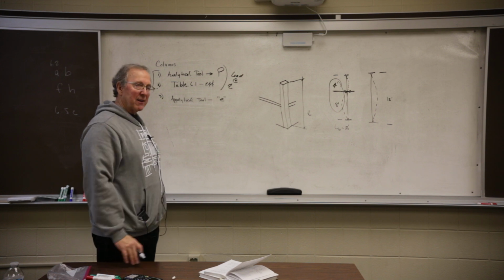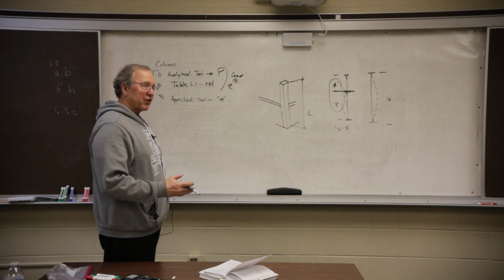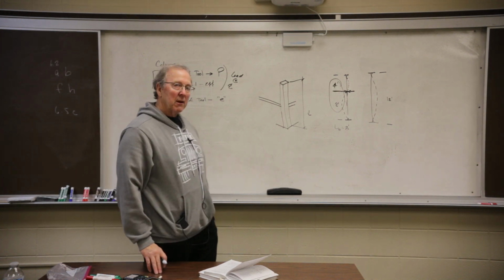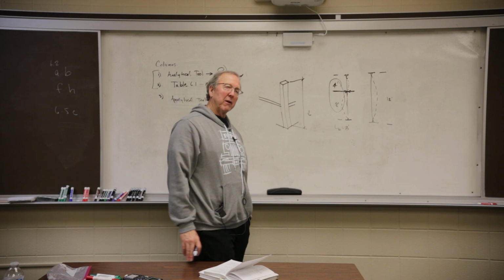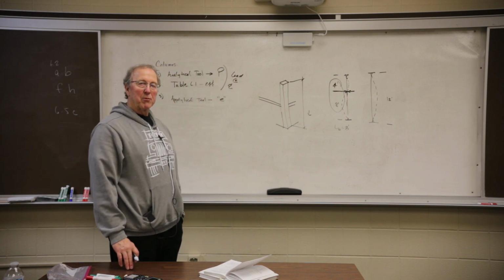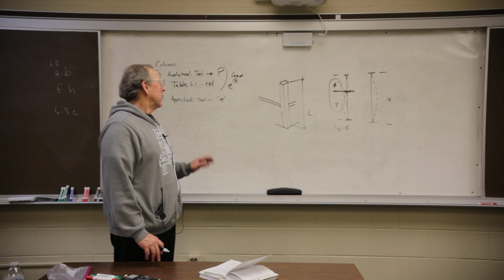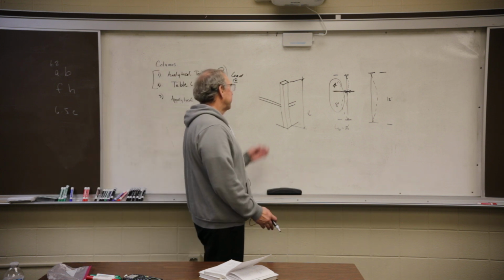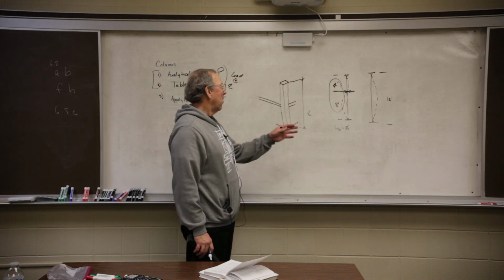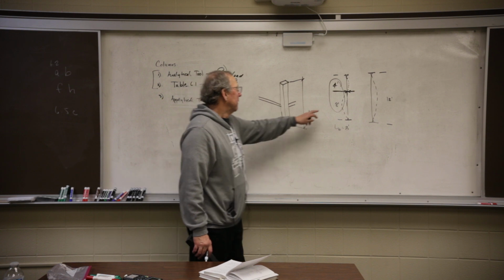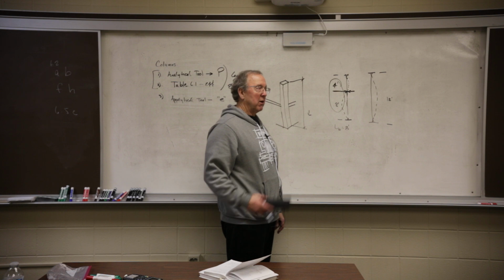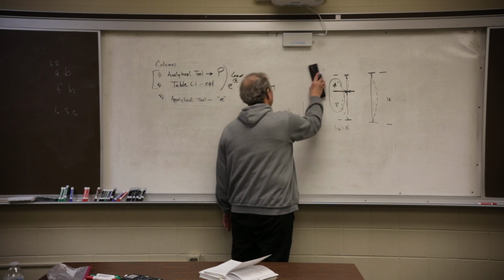So you've got to understand the concept of bracing. Bracing's big. We use it all the time. You could take a member and change its load capacity by a tremendous amount by just adding the proper bracing in it. So you've got to understand lateral support. You've got to understand the concept of lateral bracing. Even though it's 12 foot long, which this one still is, the unsupported length is 8 feet, not 12 feet. So that's that concept. You need to know that.